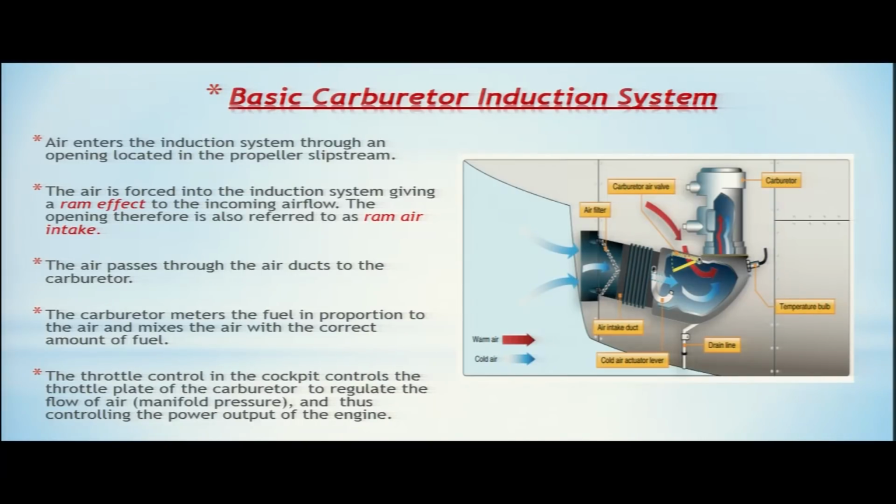Now since this opening is in the slipstream of the propeller, that propeller slipstream gives a ram effect to the air which is going inside the system. So since the air which is entering the induction system is getting a ram effect, it is also called a ram air intake. So this opening is also called a ram air intake because it is getting the ram effect from the propeller slipstream.